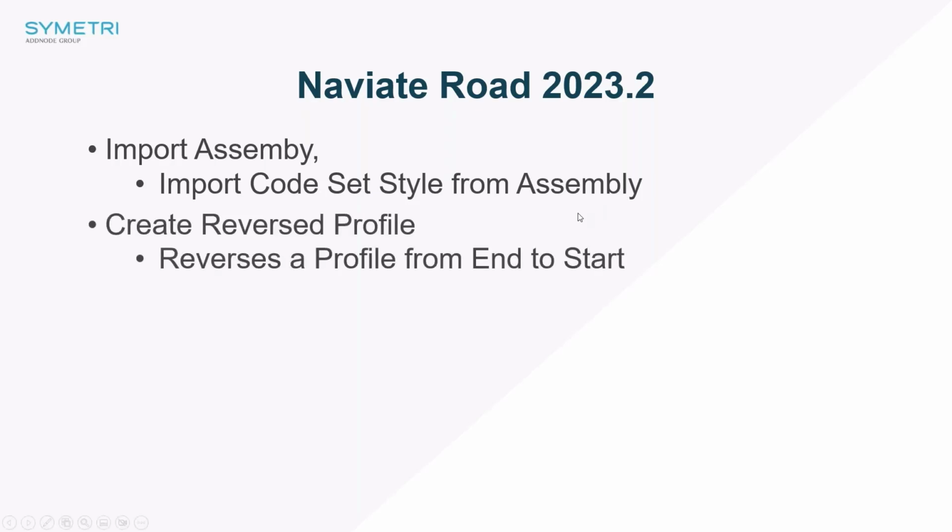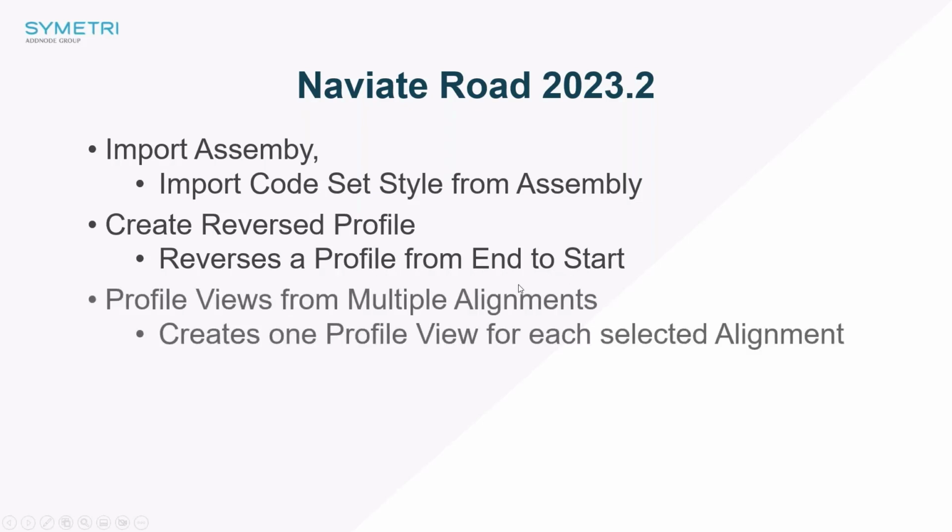We have created a new command called create reverse profile, which reverses a profile from end to start. We also have a new command, profile views from multiple alignments, which allows you to select a number of alignments and create one profile view for each of those with the same setting instead of running the same command multiple times.